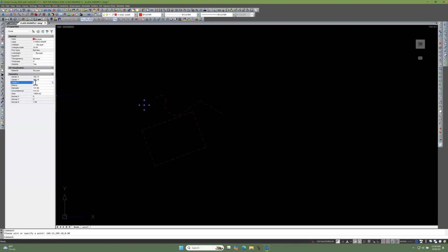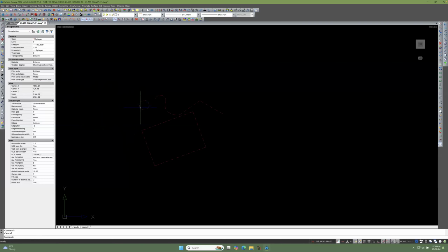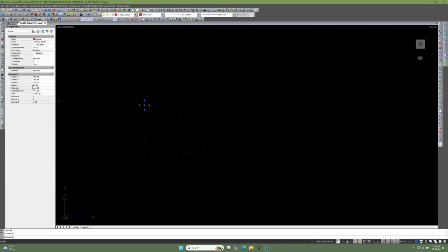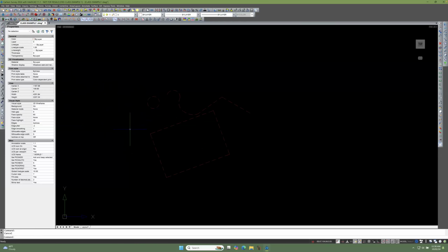You can set its elevation by making it, say, 150. And so now that has an elevation of 150. Let's change that back. Let's just make it 50 so it's not so bad. And we'll do a little shortcut trick here. I'm going to hold the shift key down and press and hold the wheel on the mouse, and then move it.